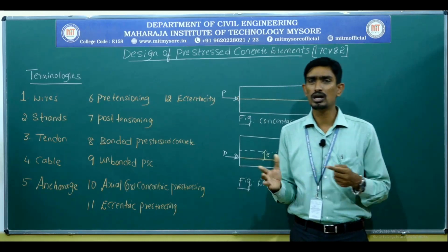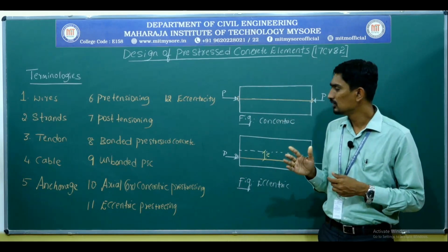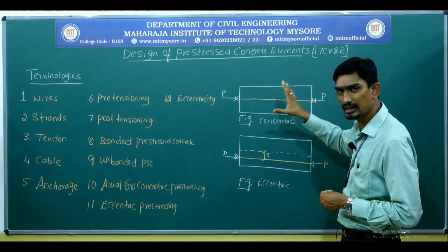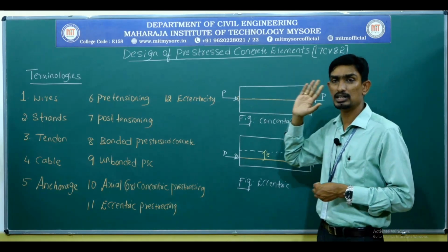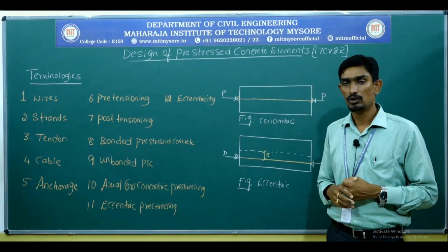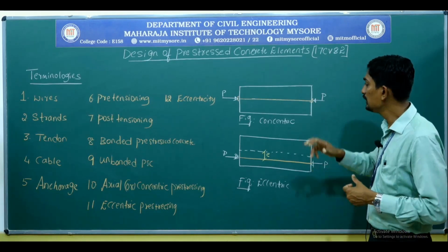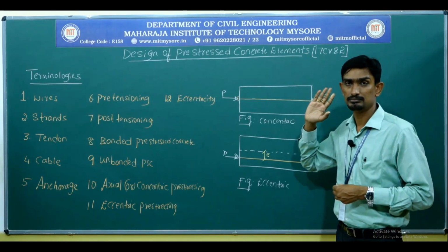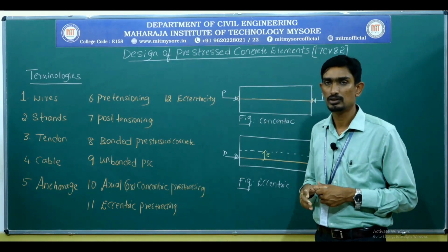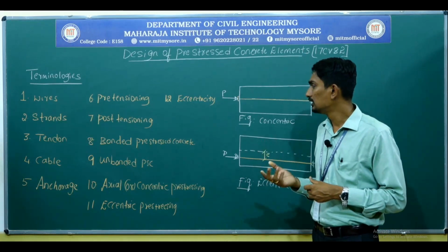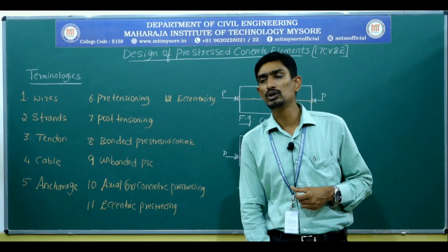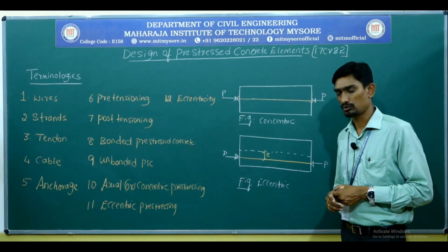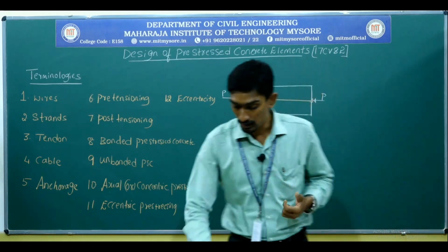Full pre-stressing means inducing the pre-stressing in such a way that no tensile stresses are developed. Partial pre-stressing means inducing the pre-stressing in such a way that some amount of tensile stress will be developed. These are the terminologies we are going to use in the design of pre-stressed concrete elements course. So with this, I will move further.